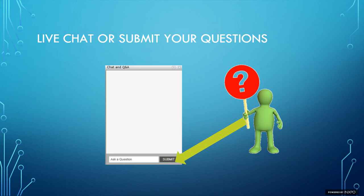Great, perfect. This viewer wants to know a specific question as well. How do you size the flow rate for desiccant dual tower regeneration? Is it usually 30% of normal flow rate? Okay, I'm not 100% sure whether I understand the question. A cold regenerated desiccant type dryer typically needs 15 to 17% purge airflow.